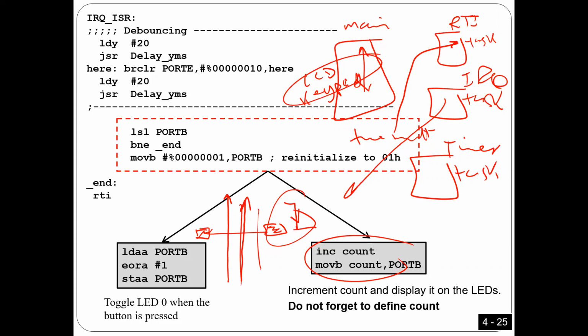So what I'm explaining is that I'm going to have multiple tasks. IRQ is going to take care of counting how many people enter the store. Every time one cuts this infrared, IRQ is going to increment the counter. This is number one. Number two, RTI can be used for time multiplexing, so this is the second task. Number three, I can put something like LCD keypad in the main, and so on. This is the beauty, the importance of interrupts, because of interrupts we can program big programs.